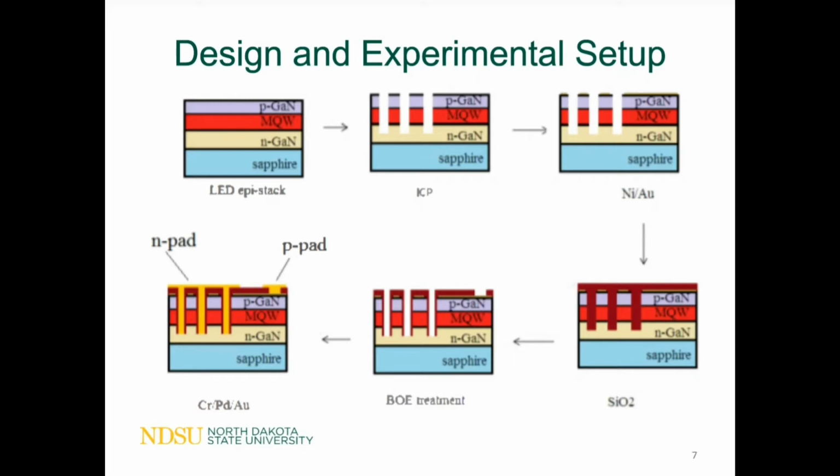Next, the LED undergoes wafer cleaning by immersing the wafer into boiling aqua regia, which is a mixture of hydrochloric and nitric acids, and deionized water. Then the wafer is ultrasonically degreased by acetone, methanol, and deionized water. The final step in making the mesa structure and periodic microvia holes is lithography, where a pattern is transferred from a photomask to a substrate.